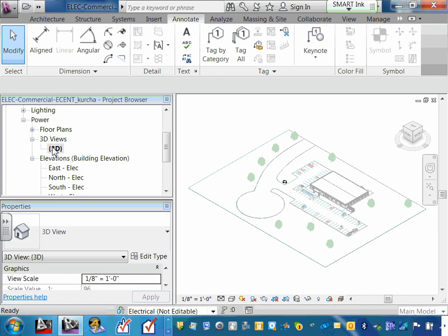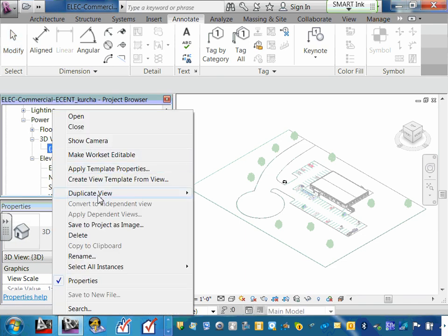So remember how we did views? Right click on a view. What did we do instead of copy? Duplicate. Wait until you hear SKM, and then we start destroy instead of delete. Anybody know the difference between destroy and delete? There's a software called SKM. If you delete things, it's completely different than if you destroy it. They use the word destroy. Destroy erases from the memory, basically the whole computer. Delete just deletes from the view I'm in.